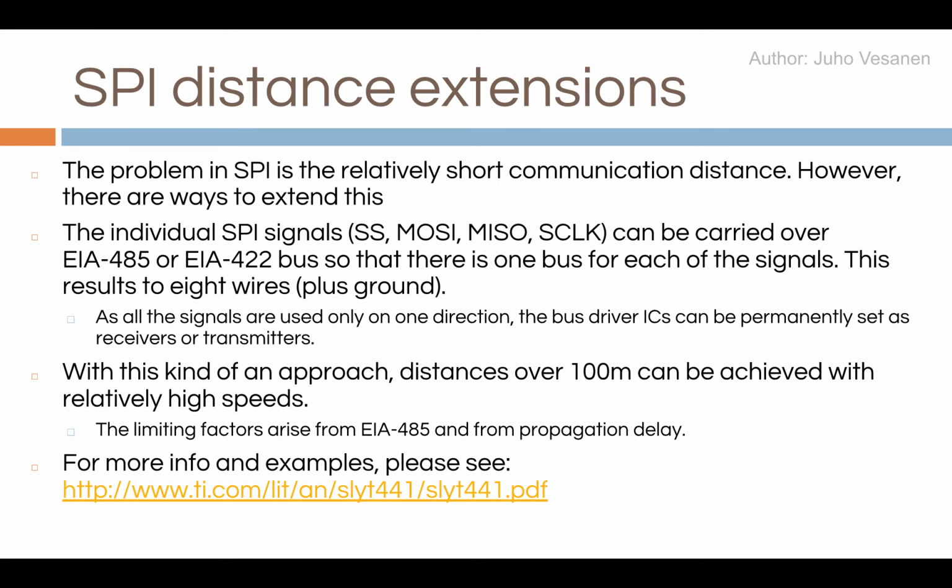Okay, SPI distance extension. SPI itself has a relatively short communication distance. However, you can use line buffers. All of those lines are one directional, which means you can just have a power driver there, probably with matched lines, so not just a single line but a twisted pair line, for example 90 ohm standard cabling.